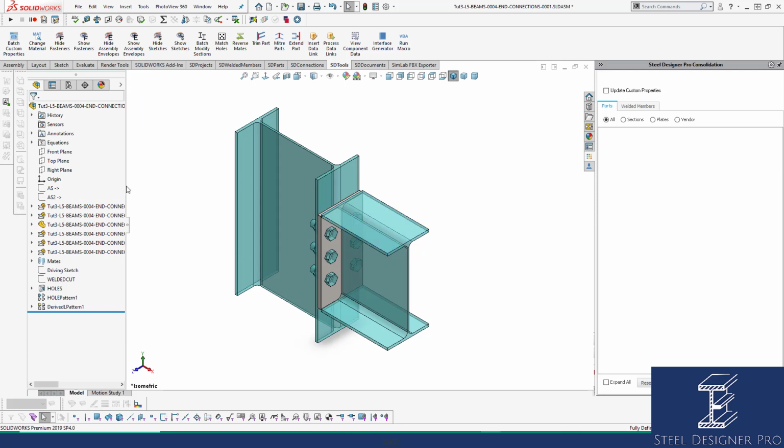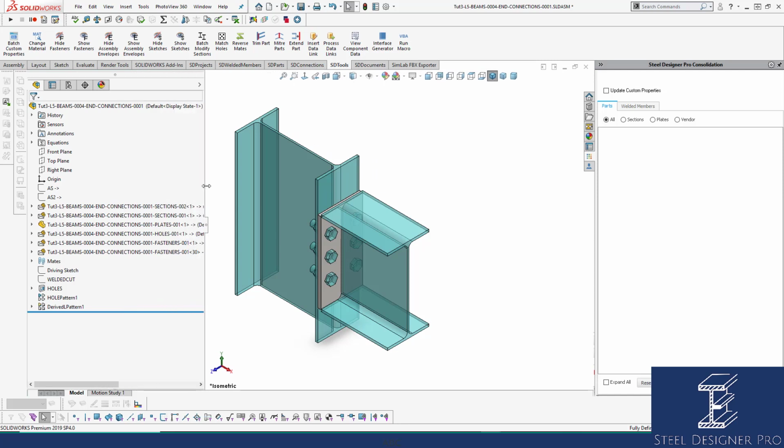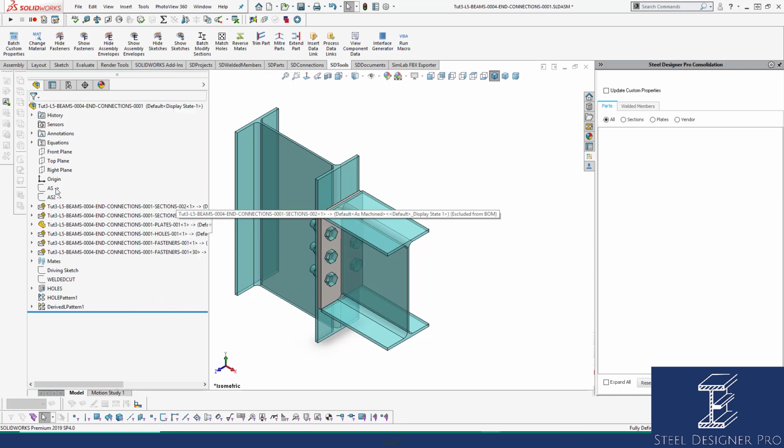Now let's have a look at what's been put into this connection. So obviously we've got our 2 attachment sketches. So the very first attachment sketch is simple and is just like all the other attachment sketches within our application. The attachment sketch is the first sketch line and the only sketch line, and it's drawn from the origin away from the origin. In this case, the column's sketch line is drawn from the bottom to the top,